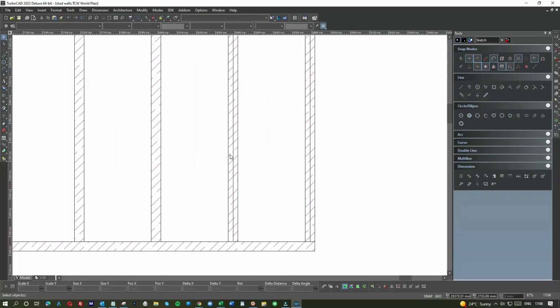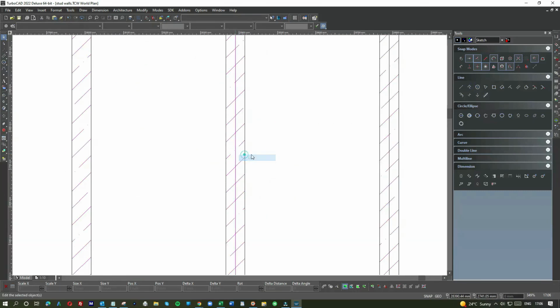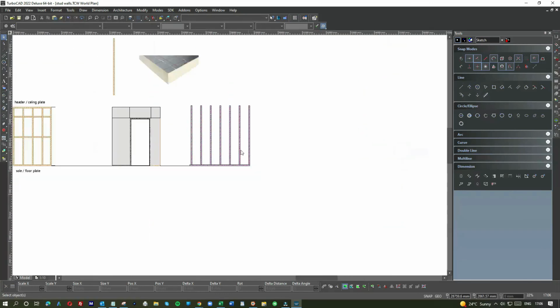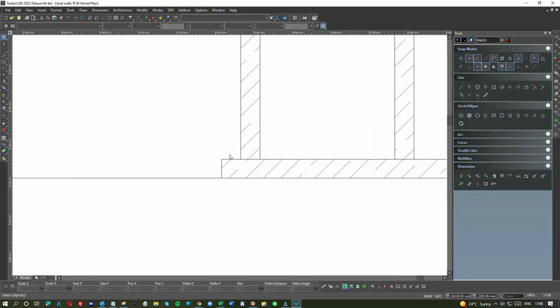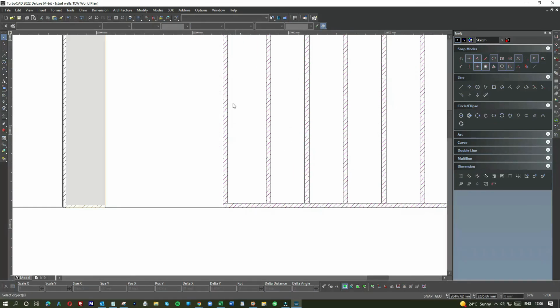And then I'll explain. So we started off and we've done all the uprights at 400. So here now, as you can see, the upright, we've got a little bit of space left over. Now, because it's only 50mm, I wouldn't necessitate putting in a stud and then putting a second one beside it. So I let it go.